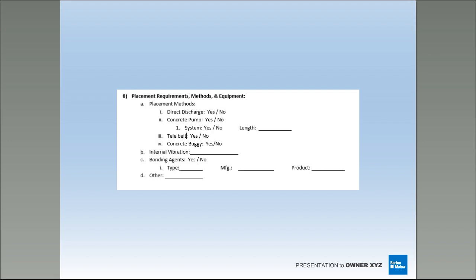You're going to have to use a concrete pump at times. Just make sure your mix design reflects pumping. And we'll get into that. There's certain things you do for that. But again, always ask the question how they're placing, right?